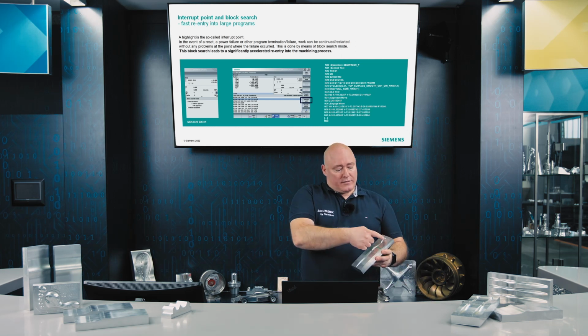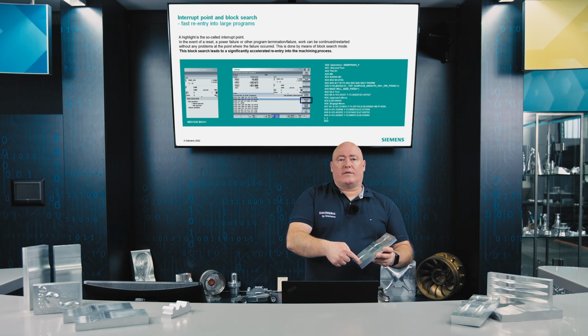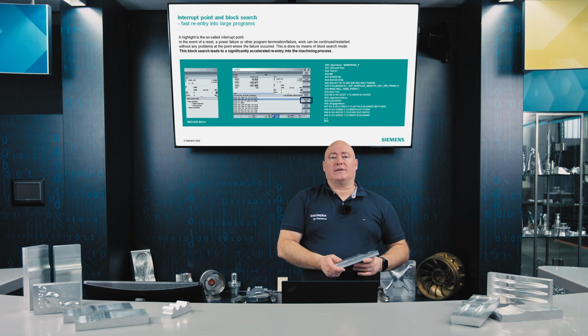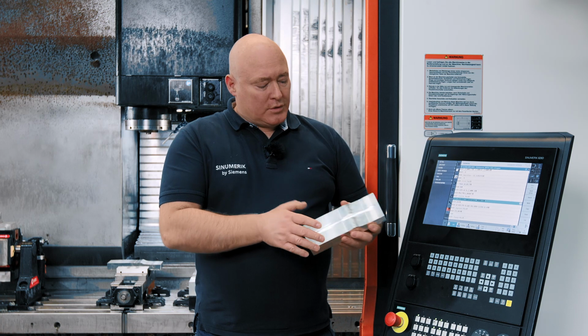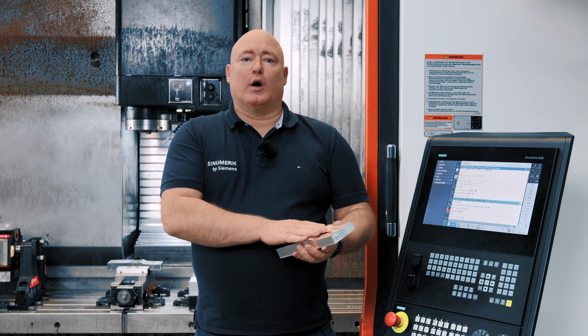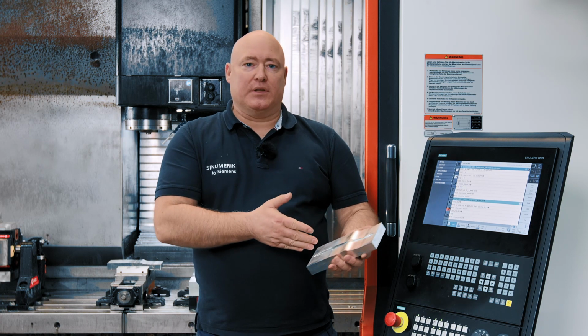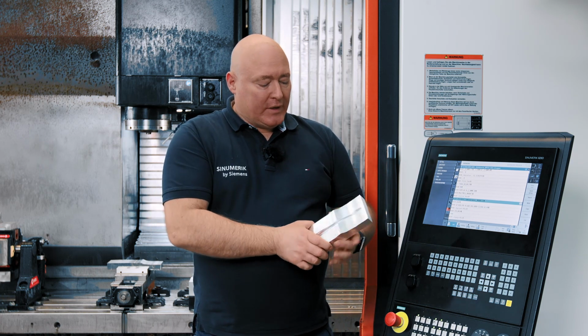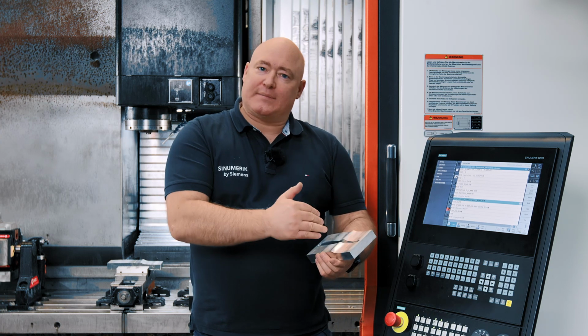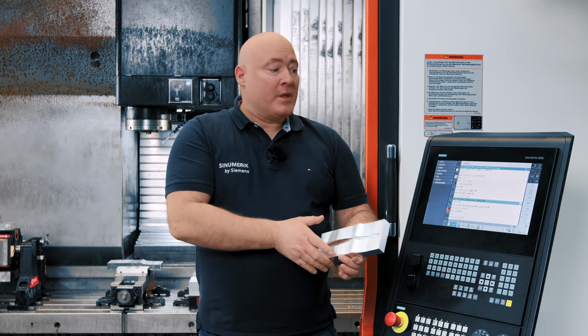And how machining of freeform surfaces or milling of freeform surfaces works, I will show you directly in practice on the machine. Our finished workpiece is the bottom of the injection mold of our toothbrush mold. As mentioned, this is realized by the roughing operation, residual stock removal, and finishing.